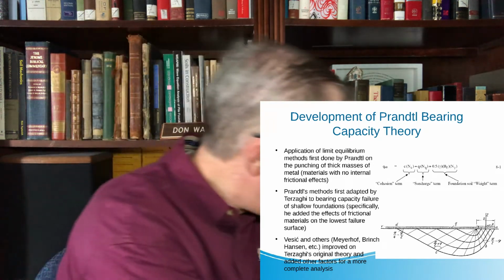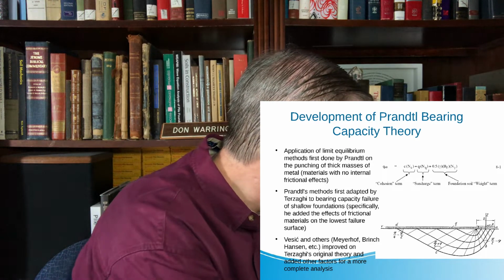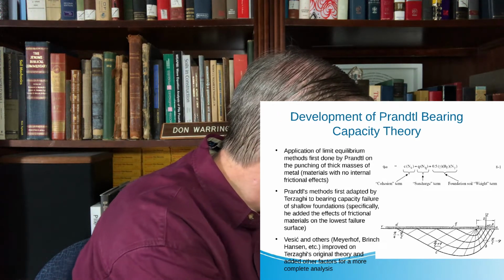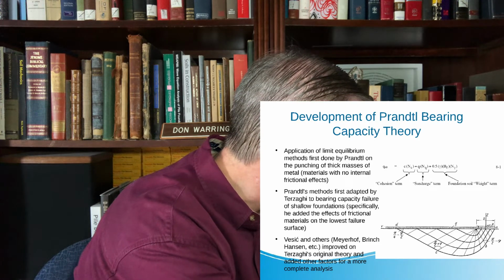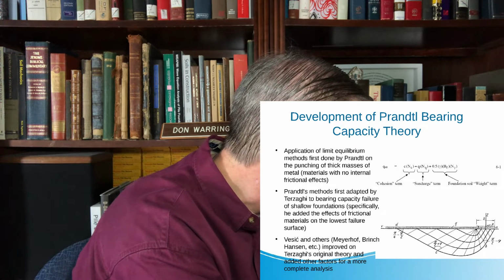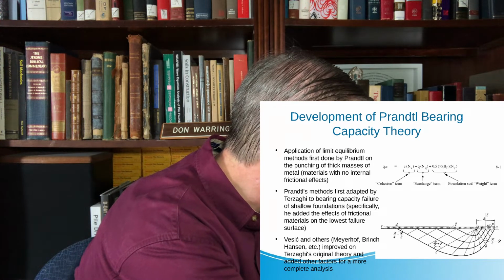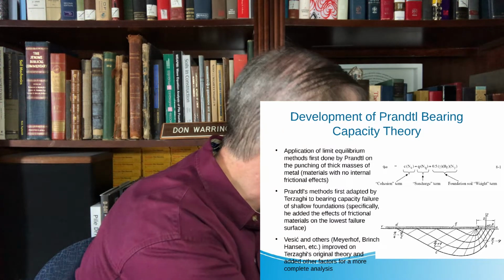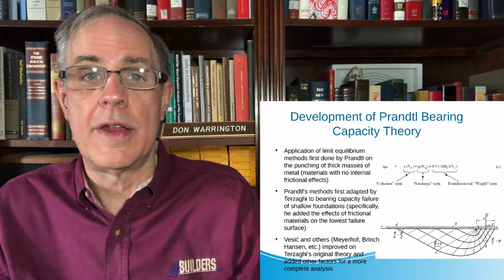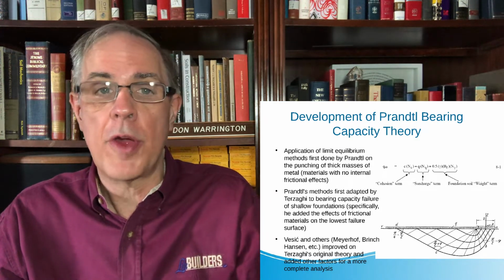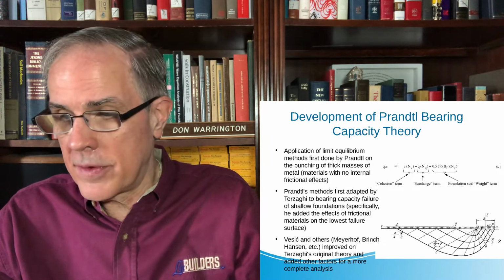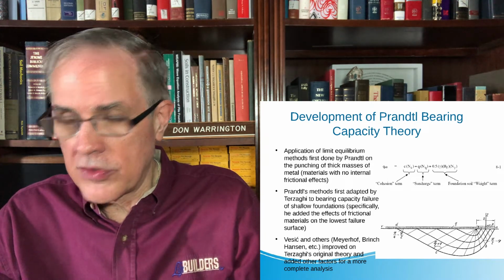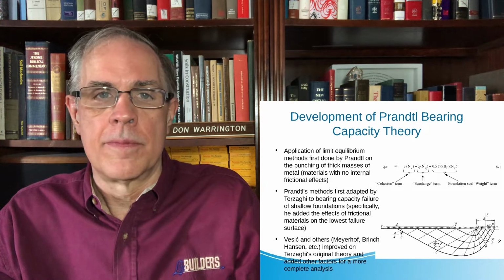If this is the failure surface, and that's Prandtl's, then inside of this there is a mass of soil, and that mass exerts weight that can be used to resist along the surface, much as is the case with slope stability. Same thing. And that's the last term, the foundation soil weight term.